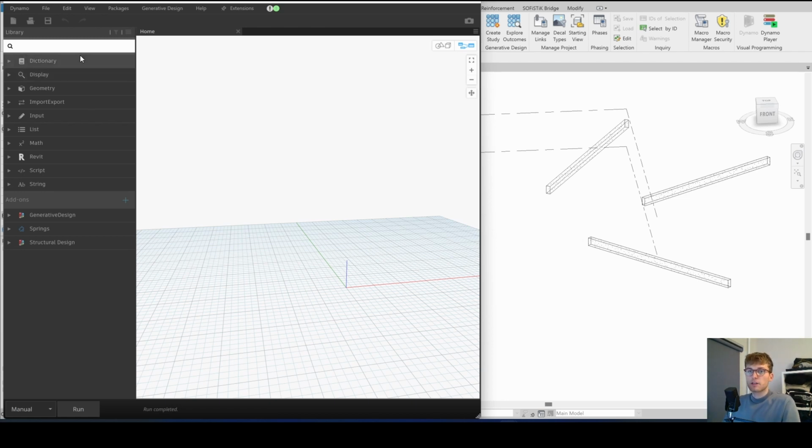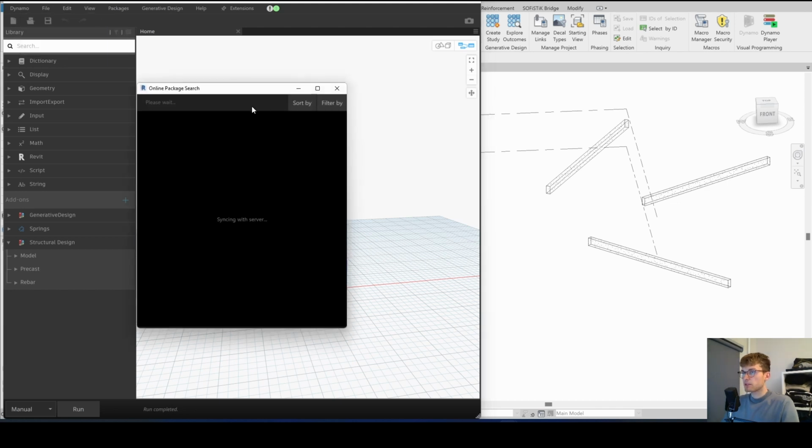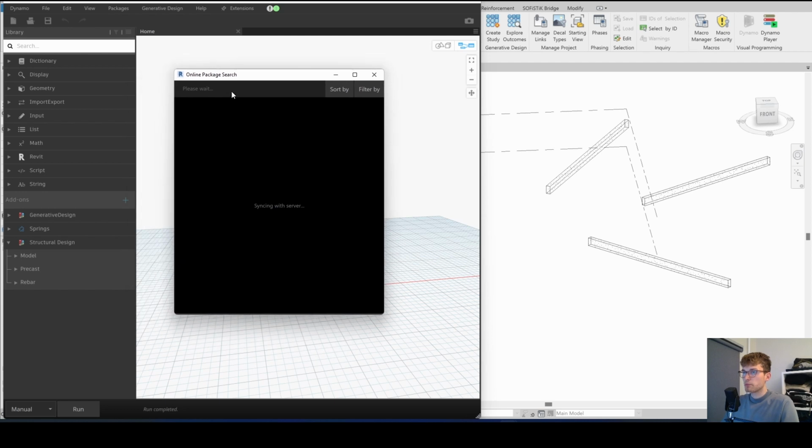Okay, let's start. So as always, those of you who have seen some videos of me, I always like to start off with the end. And as in other videos, we need the structural design package. In order to get that, simply go to packages, search for a package, then this package search window opens up.